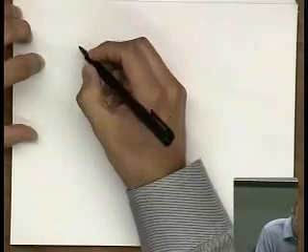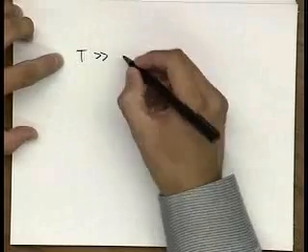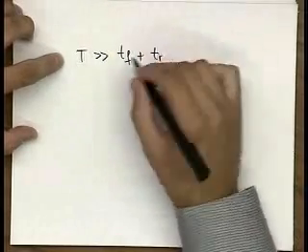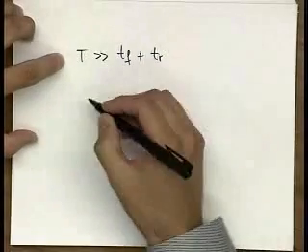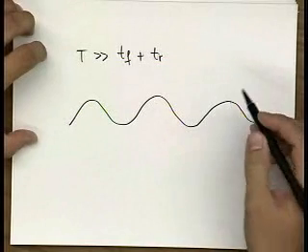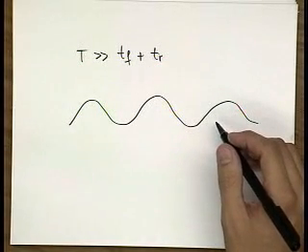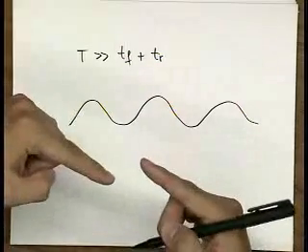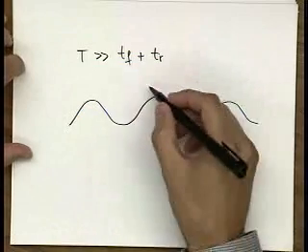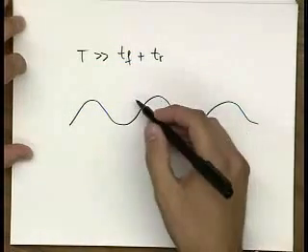So we have this relationship that the period of oscillation has to be significantly larger than these rising and falling delays. And if you have a very small number of stages, then you more likely have a sinusoidal wave, and it's not really quite going to undergo the full rising transition by the time it's getting triggered with another transition and wants to go low. So you may have a reduced swing and also not so good signal slopes.